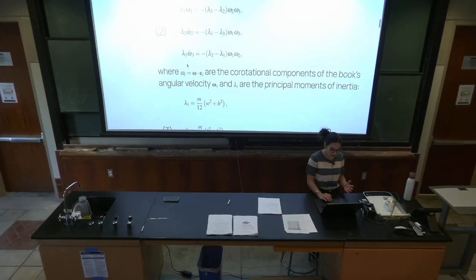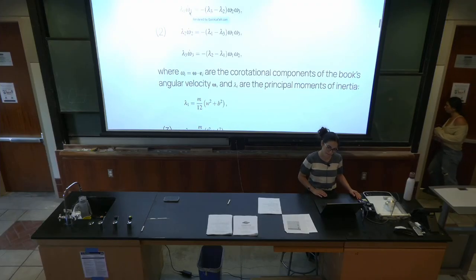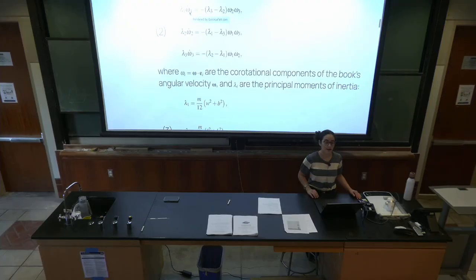These three equations need to be satisfied. The coefficients are different. So you can think of, if I'm rotating about omega 1, if lambda 1 is minimum, then to maintain some equality, omega dot 1 is going to be greater or something like this. So the three differential equations of conservation of angular momentum are satisfied throughout the motion. Okay, so then the actual components of omega will change as long as the I omega vector does not change? Exactly. Okay, thank you. Exactly.